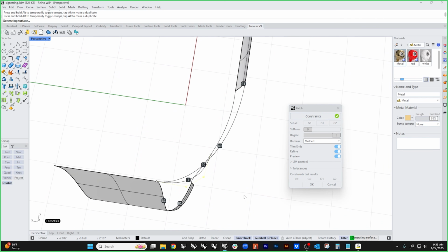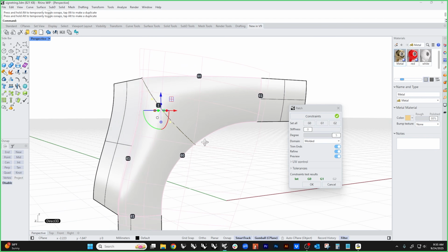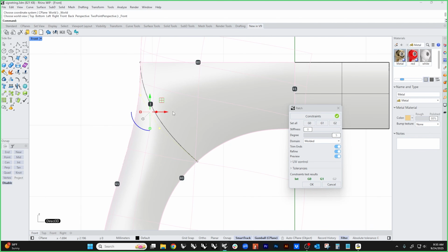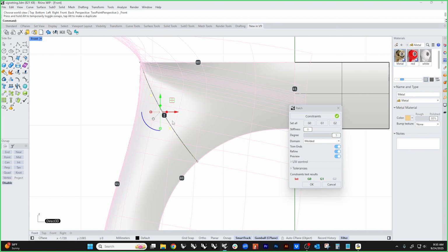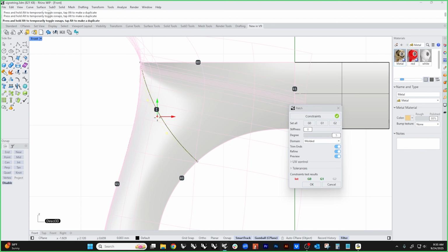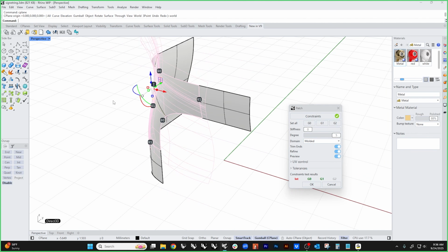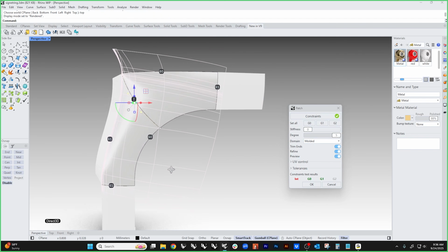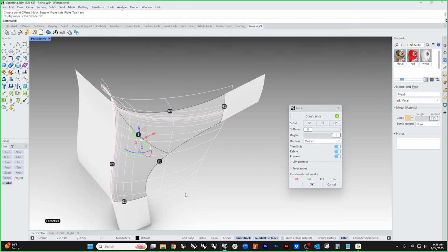So now I can come in here with these sculpting curves and really fine tune this thing. If I go to the front view, I can say, well, that shape is kind of drooping a little bit. Let's pull these points over a little bit, straighten that out. And that highlight's going to change. And I can say, I don't really like that. I'm going to put it back over where it was. Or maybe I want that highlight to change a little bit and come this way, modify the bias. That's starting to feel really interesting. And if I go into rendered mode, I can see the highlights on that, how that's looking.